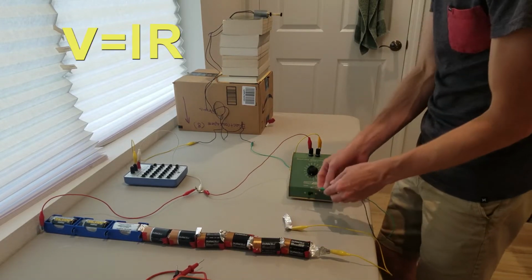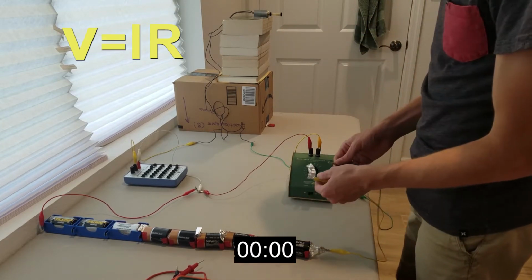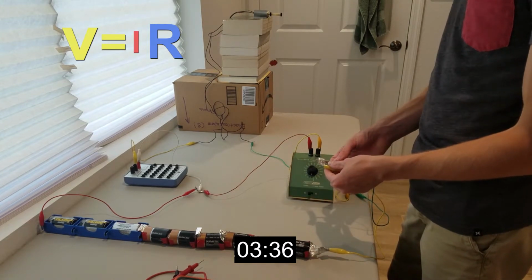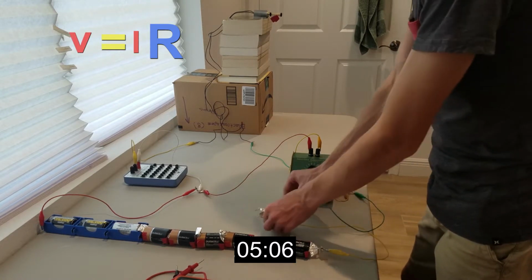Using Ohm's law, V equals IR, looking at just the motor, we know that the resistance of the motor is constant, but the current decreases. This means that the voltage drop across the motor is also less than before, meaning an increase in the time interval, as observed.